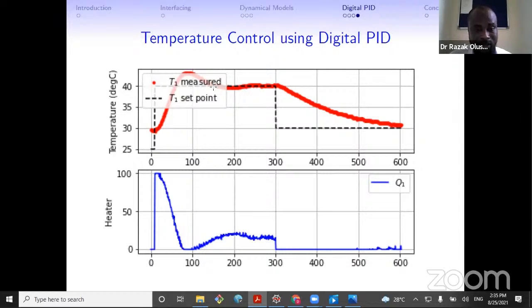As you expect, once you heat up the transistor, there's usually a delay before the effect can be felt by the temperature sensor. So even if you send the right control signal, before you can sense the correct temperature at the output, there's a delay. The effect of that is that you keep increasing the control effort you are applying, not knowing that it has actually been affected. So this will lead to saturation itself. And more saturation also leads to more delay.